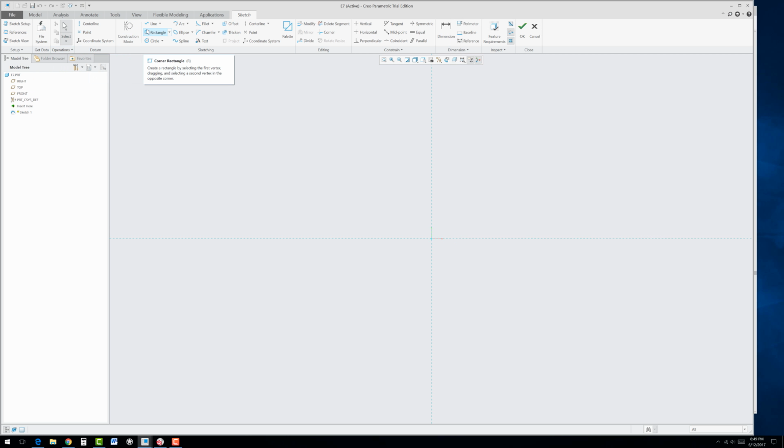So with that being said, take the line tool and first draw out a short little vertical line and middle click a couple times. Let's just get that to size, about 1.5, and then go ahead and hit delete on your keyboard to delete or weaken that dimension. Or you could click on it and hit delete on your keyboard and make it a weak dimension.